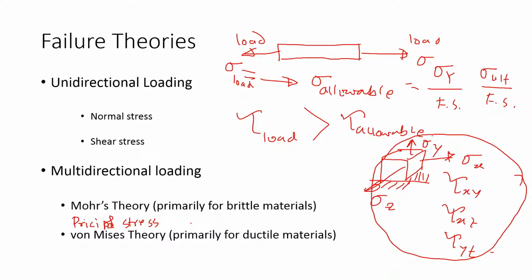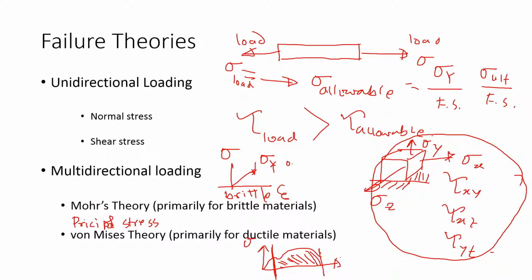However, what we are discussing here is how material can fail. Now if you remember that stress strain diagram, for brittle material, it fails right there. So this is for brittle material. Now for the ductile material, on the other hand, it looks quite a bit different. So it goes under plastic deformation. So this is up to the yield point, and you can see it goes through quite a bit of plastic deformation. So the yield point for the brittle material or the ultimate is almost the same point, and then using that for all kinds of designing is probably not a good idea.